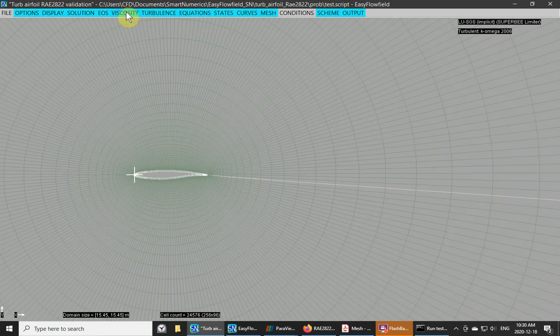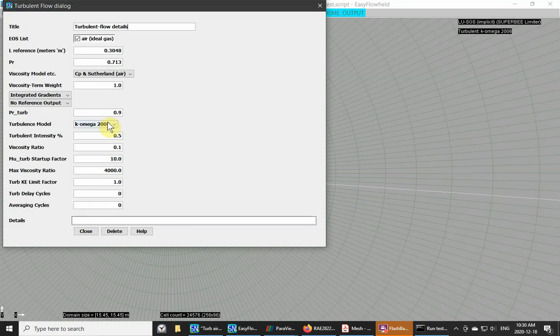Once you've chosen the viscosity and turbulence model, then you have to choose the flow type. So you could have run an inviscid simulation or a laminar simulation, but in this case I'm running a turbulent simulation, and I'll only discuss this parameter here, which is being set to the size of the chord, which is 1 foot, but expressed in meters, and that is used as a reference length to output the Reynolds number based on chord, which will be discussed later in this video.